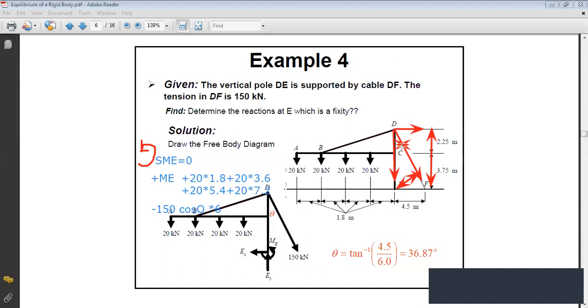It will be D sine theta, okay? So here, when we replaced for the X component, it's D sine theta, okay? So if I do it by another method, I will obtain the same result because the projection, this distance, is equal to D, which is 6 times sine theta. And then I multiply by the force, which is 150. So I end up with the same moment, okay?